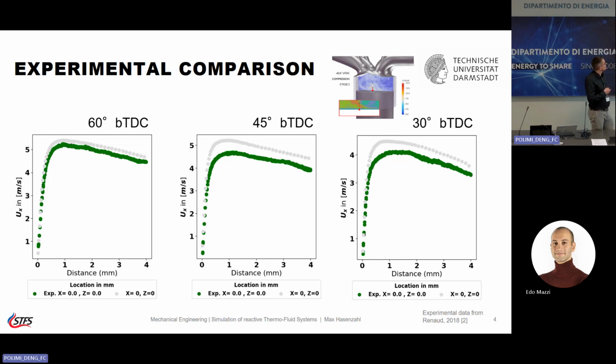And you see quite a typical velocity profile for wall-bounded flow. Really steep gradients at the wall, and then a maximum velocity, and obviously because you have a tumble, velocity decreases towards the center of the in-cylinder region.